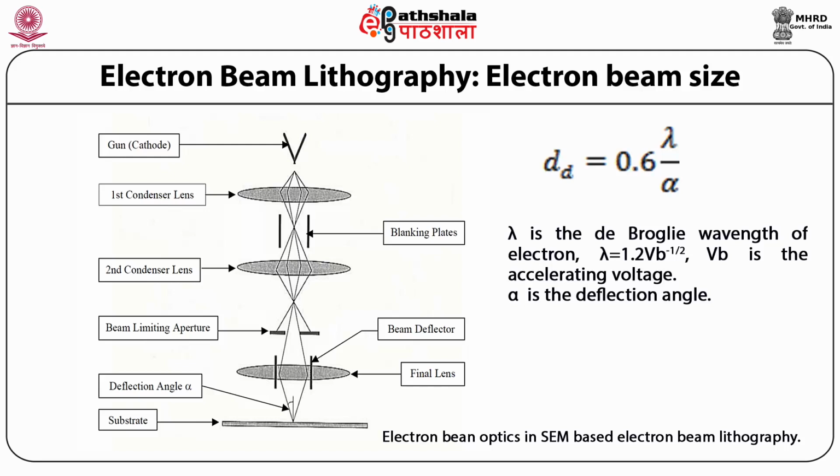A differential voltage applied to the parallel plates results in a perpendicular field gradient which deflects the beam off axis. Hence, by varying the electric field, the degree of deflection of the beam can be varied. Similarly, varying the current through a set of deflection coils can also be used to deflect the electron beam off axis.